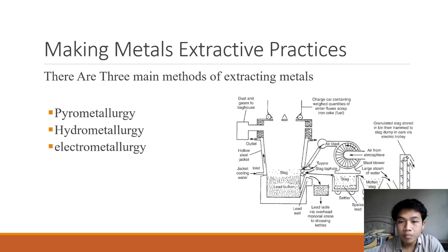And let's talk about pyrometallurgy. Pyrometallurgy is the extraction of metal from ores by chemical reaction at high temperature. In a fuel-fired furnace, pyrometallurgy may involve roasting and/or smelting for the extraction or refinement of metals. Smelting refers to a melting process that separates metal in fused form from non-metallic materials.